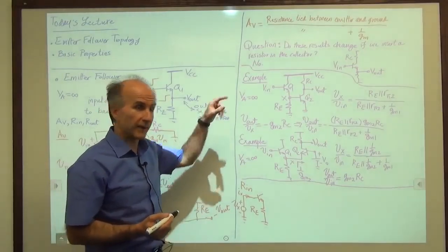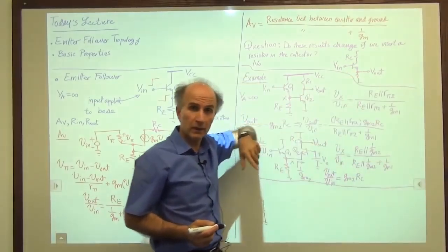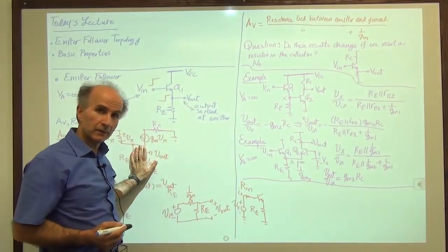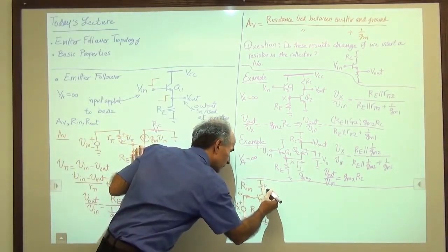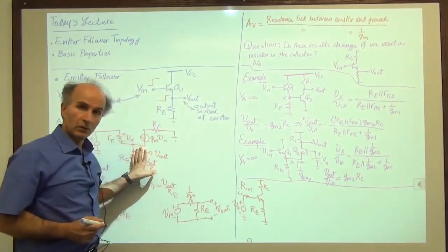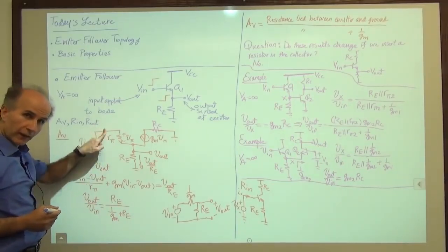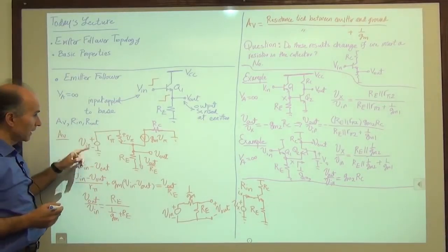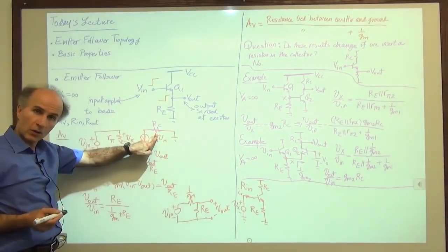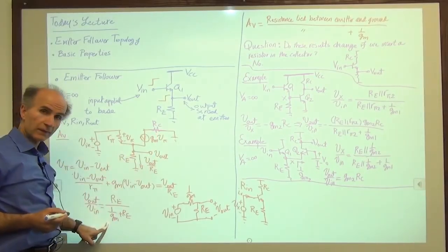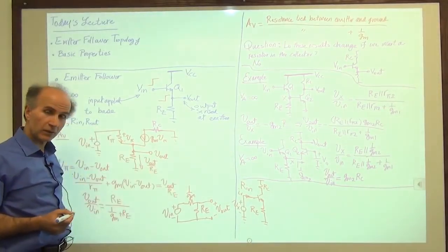Okay, now remember what we just said. We said whether we have a resistor in the collector or not, this circuit doesn't feel it. So does it matter if I add a resistor here? No, because you can again think about it this way. I'm interested in this current, right? V in over I in, or Vx over Ix, would be the input resistance. Now, does this current get affected whether we have RC here or not? No, because none of the equations that we wrote here changes, right? So I in doesn't change, V in over I in, or Vx over Ix doesn't change.